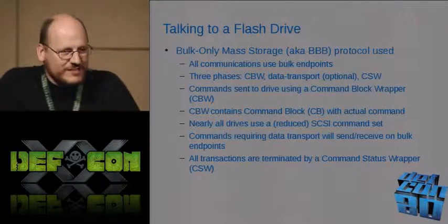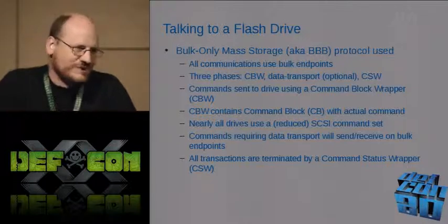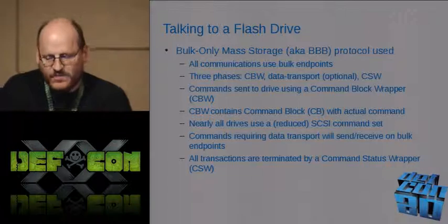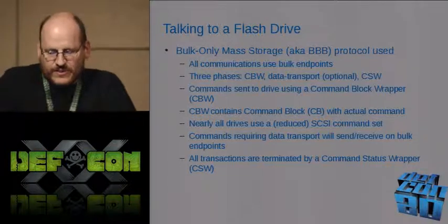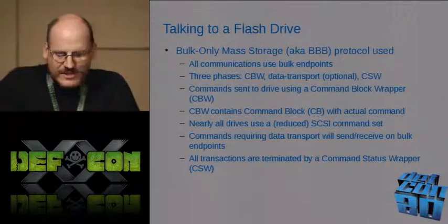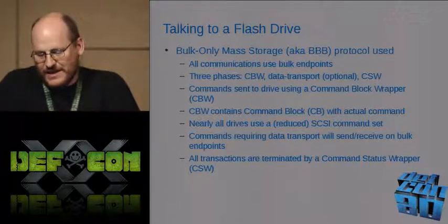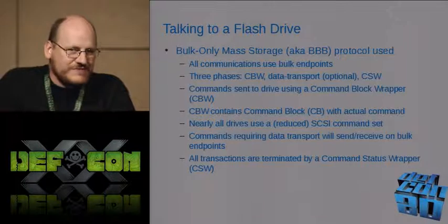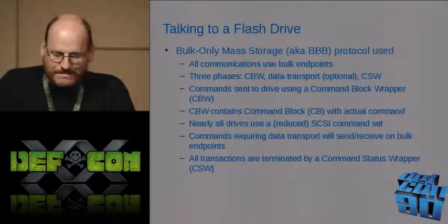Data transport, depending on the command, and then a command status wrapper where you say, hey, did this succeed or not? All right, so most of these drives use a reduced SCSI instruction set. And if you have to send or receive data, you use a bulk endpoint for that.